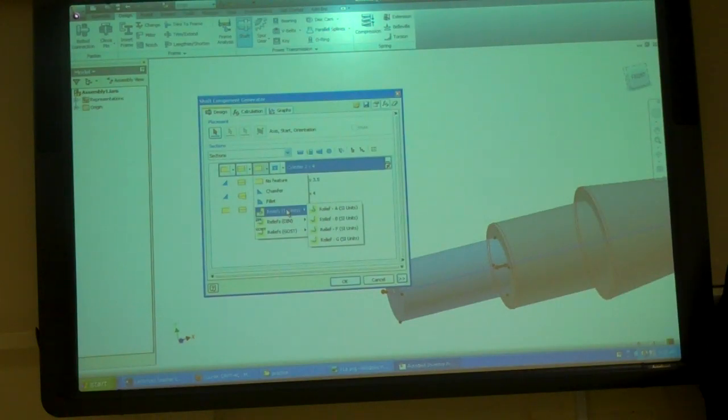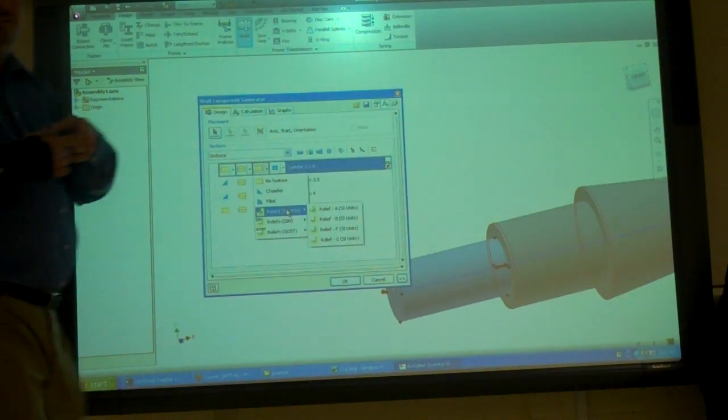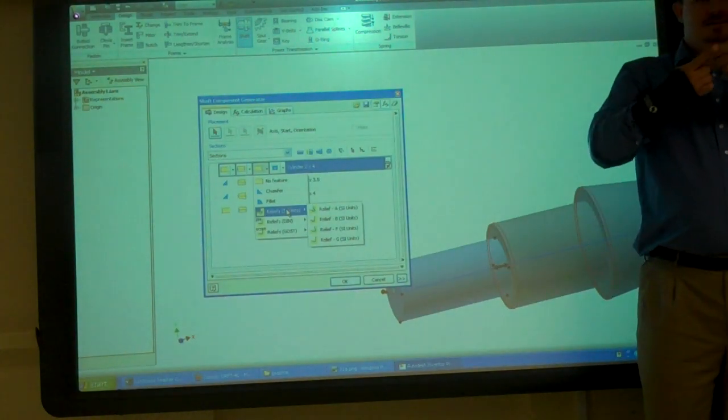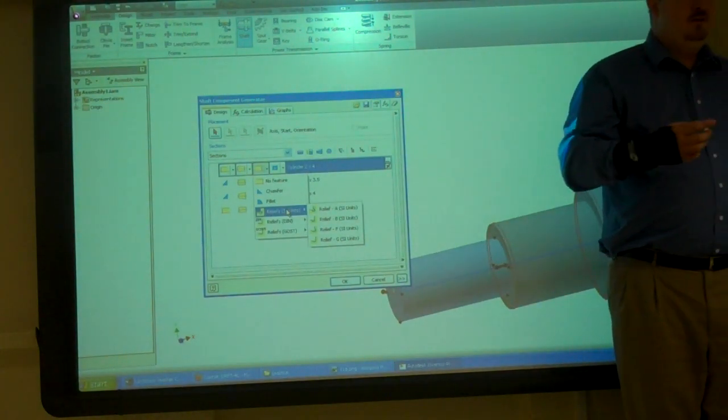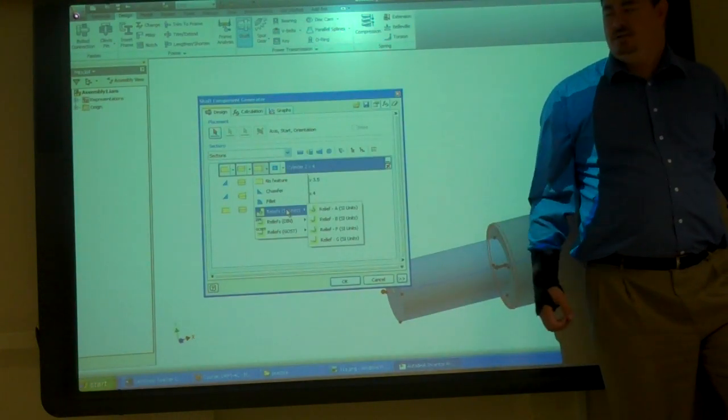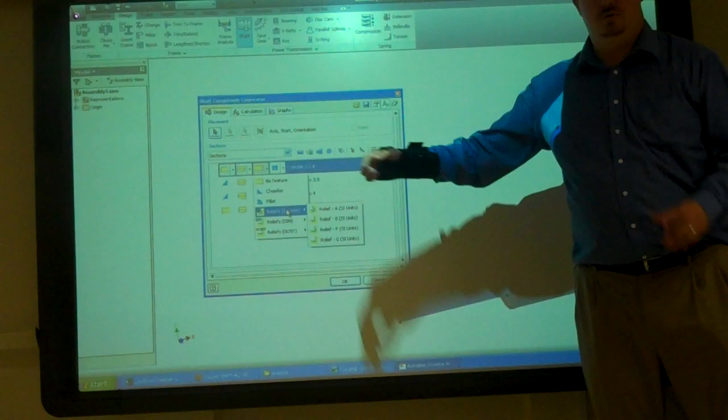When I just do this, the black corner is just sharp. Yeah, when you have curves, it's stronger, because whenever there's a sharp corner, it's a breaking point. But also, it's really hard to get a sharp corner on a tool. Cutting tools can't really have exact points, because the point's just going to break off. So cutting tools always have some kind of a radius on them, so that they'll actually last. So that's why we'll do that.